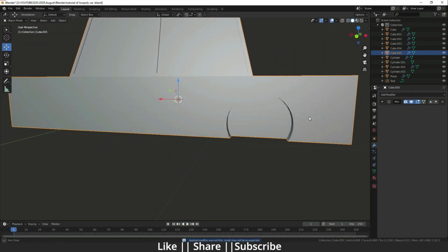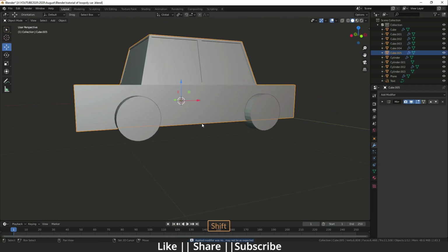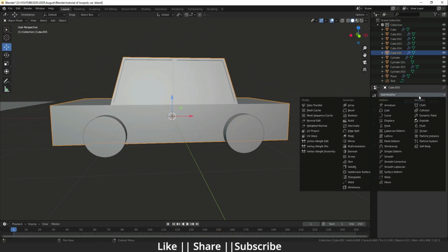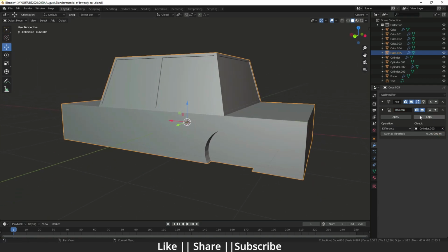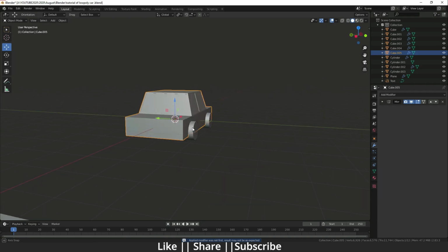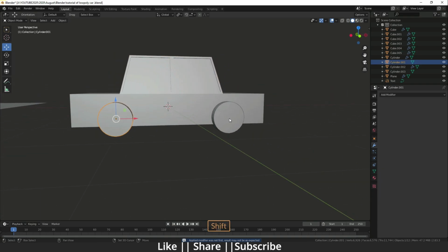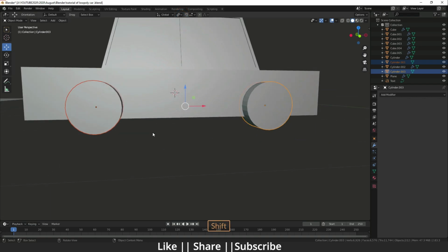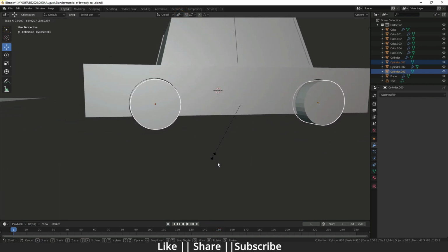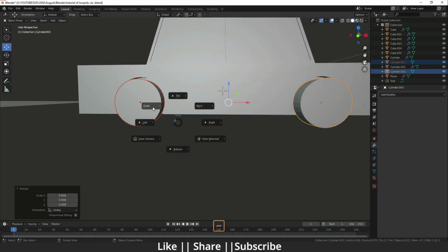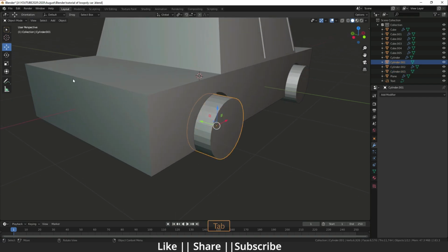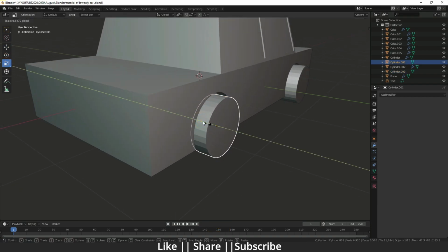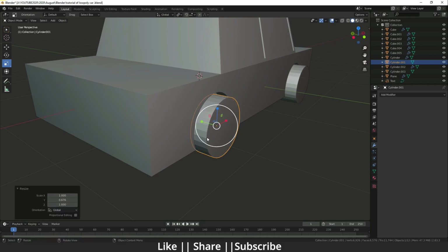So here you can see we have a perfect shape of tire here. Okay, and same thing I will do here also. So I'm just going to boolean again, and I will do like that. So when I apply it, here you can see we have a perfect shape. So now I'm just going to scale it. So before scaling, make sure you are on individual origin. Okay, and I'm just going to scale a little bit like that, and that is enough now, I think. Yeah. Okay, so now I'm just going to make a tire. So before making the tire, I'm just doing a little bit of scale like that.